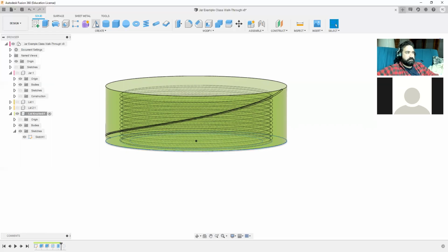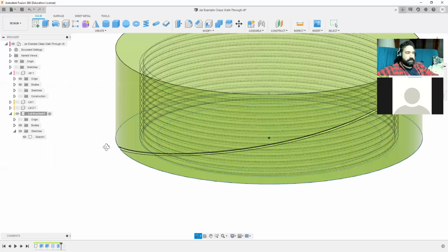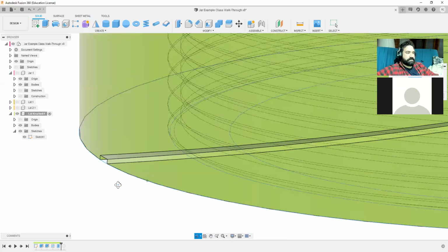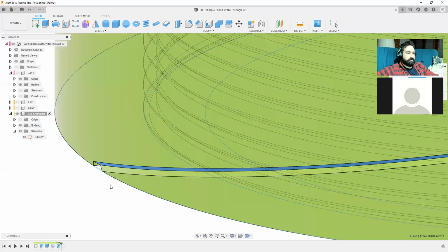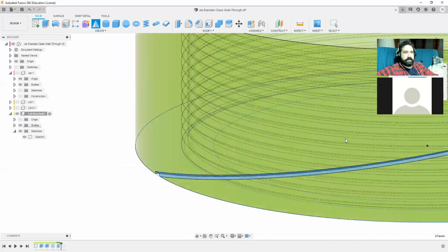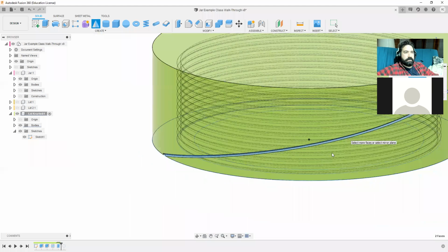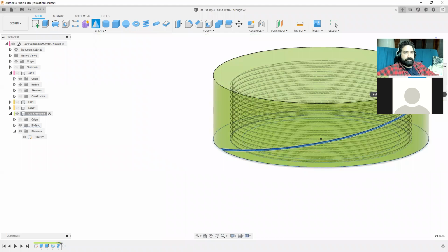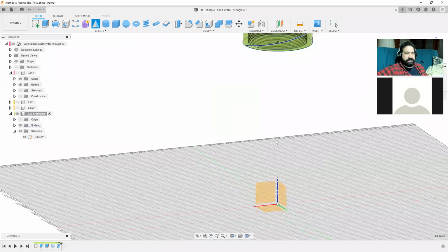So I'm going to select mirror, type faces, same. Make sure you select both of those. Mirror plane. It's asking not for a point or an axis, but for a plane, and you can use the origin plane for this. Now, the trick is, what half did I work on?